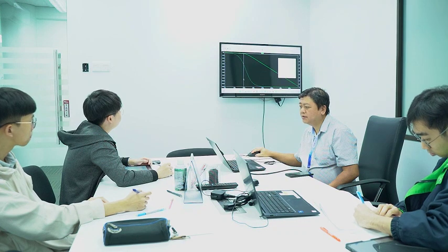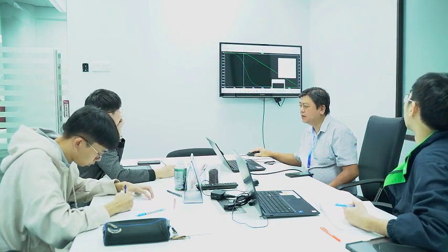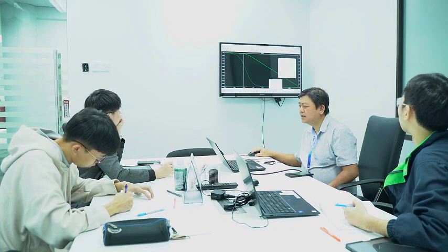The full cycle of the clock is 360 degrees. So 1 megahertz is my time. Now let's say I want to find at 100 kilohertz, for the signal coming in, what's the phase shift? Let's say it's 30 degrees. So I put 30 degrees here and I put T here. This T defines my delay between my input and output signal.